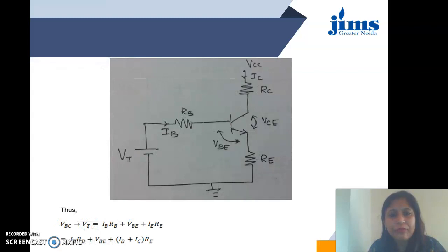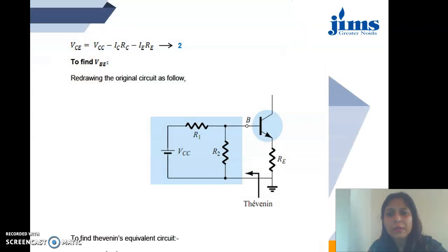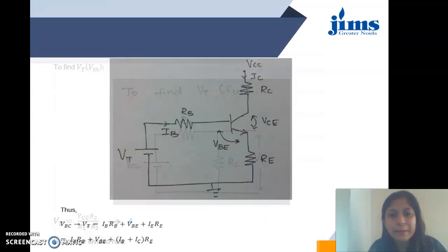Now after that we will come to this circuit where RB will be giving the Thevenin resistance and Vt is the Thevenin voltage, and after that the circuit is the same as it is. So the circuit outside the arrow, on the right hand side of this arrow, let me show you. This is the arrow, and the output side of this arrow will remain the same, where the left hand side of the arrow has been converted into the Thevenin equivalent circuit, where the circuit consists of a Thevenin voltage source and Thevenin resistor that are connected in series. So this is now the simplified circuit of